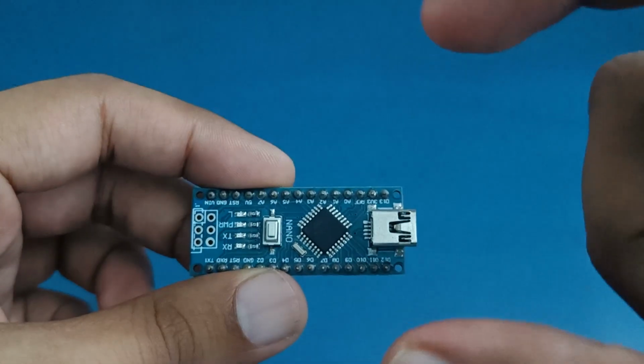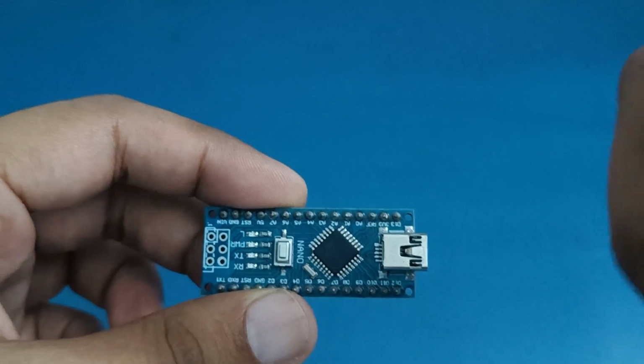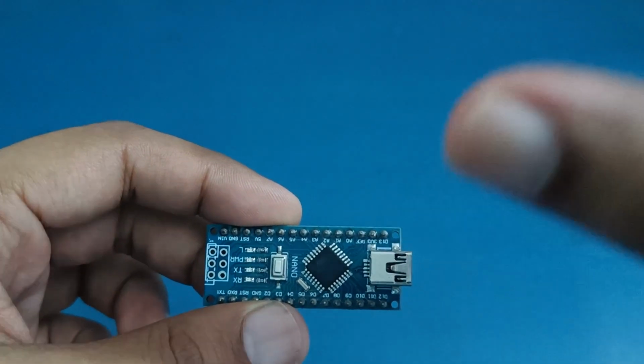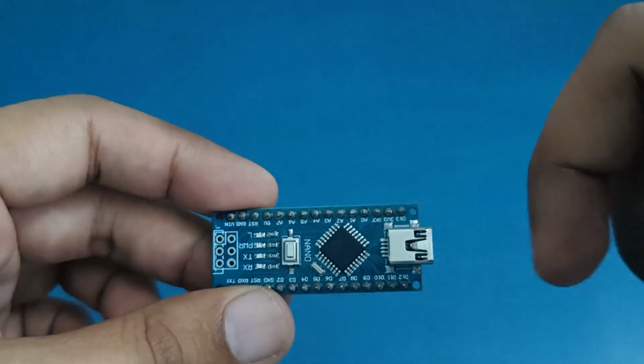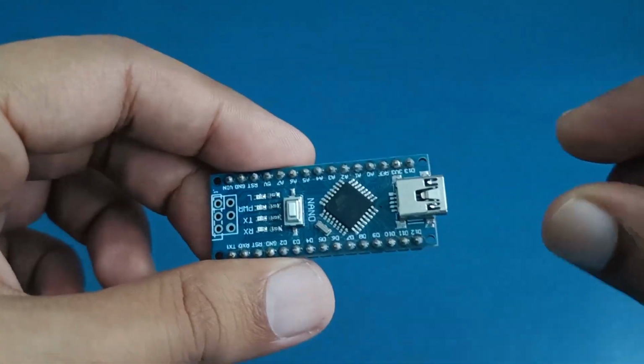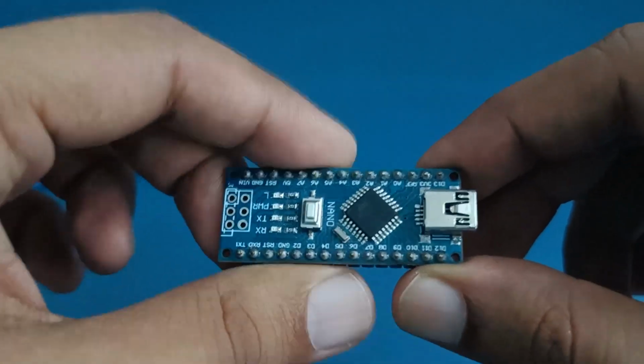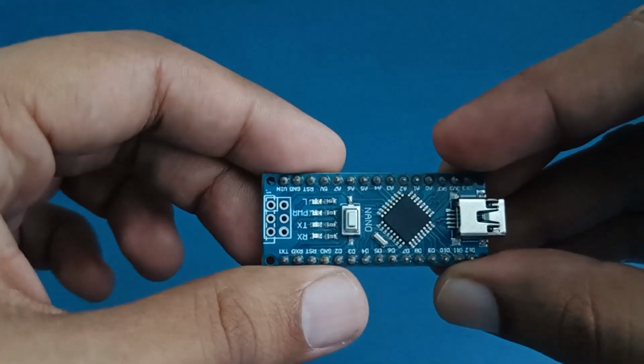A single entry contains a domain name, username and password of 45 bytes: domain name of 15, username of 15 and password of 15, so total 45. So in that way we can store the username, password and domain name in the EEPROM. We can access it using serial communication.